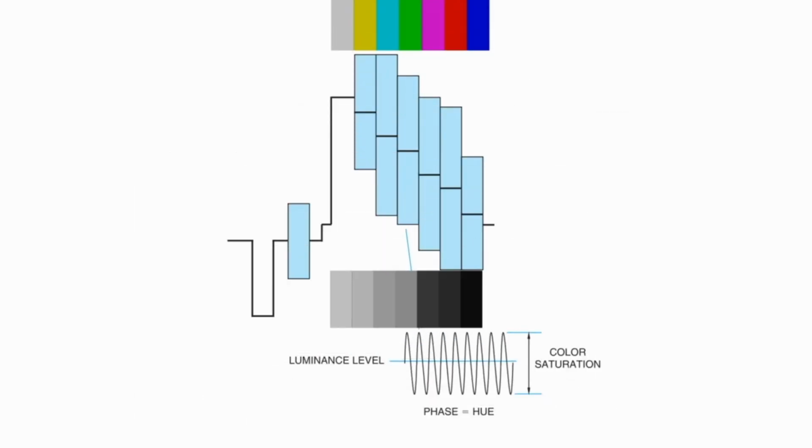Another clue comes if we look at the color bars in black and white only. Here, the brightness decreases smoothly from left to right, just as the average of the waveform does. The brightness, or luminance, of the image, regardless of color, is effectively the average of these oscillations. We need 2 more numbers to characterize colors. The amplitude of the oscillating waveform indicates the saturation of the color. White, black, and grays all have low saturation. Bright red, blue, green, yellow, purple, cyan, or any other pure color has high saturation.